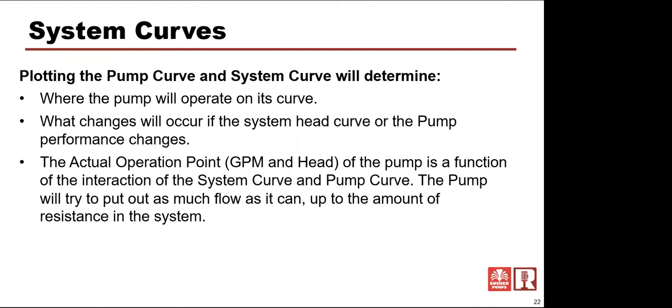We've had systems where they were having seal issues, and come to find out that for whatever reason, they may shut off a couple pumps at night and just leave one circulating. Well, the problem with that is the system was built for maybe 3 pumps in unison pumping into the same header. And with one pump only operating, there's nowhere near enough resistance. So there's a lot more flow.